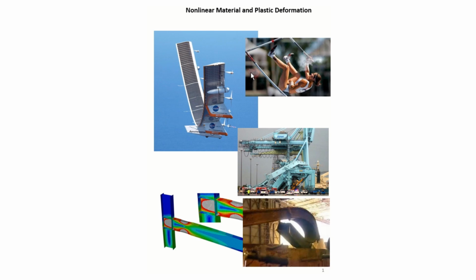Here's another unfortunate failure. We can see that the pole bent. It's kind of interesting to think about if the pole broke in the locations you would expect, where the moment would be the largest. Here's an extremely catastrophic failure. It's a loading dock. You can see the size of these members and columns compared to a person and all these vehicles down here. So this thing is extremely large, and these large beams have just completely bent over and broke and failed in a plastically deformed manner.